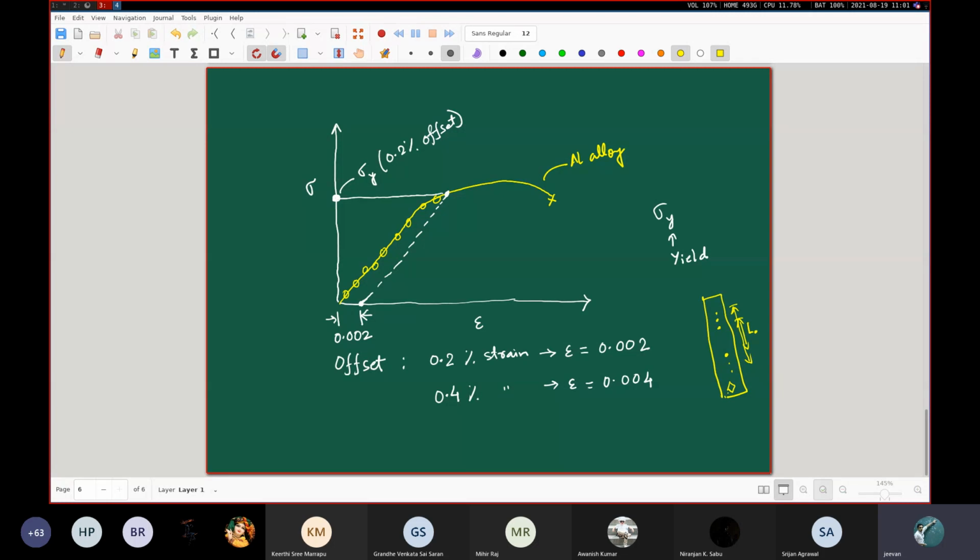So for example, what you are probably saying is, why not stick a bunch of strain gauges along this? So maybe we put a strain gauge here, here, and here, calculate all the values of the strains in this direction, average out from these various strain gauges, and then maybe we get a more accurate picture. Something like that you are probably saying, right?